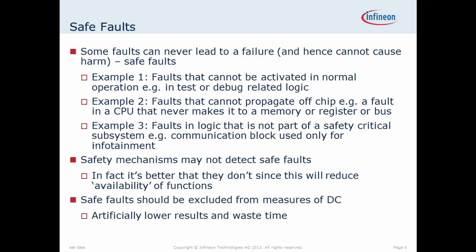So now I come on to safe faults. Some faults can never lead to a failure that can cause harm, and these are called safe faults. For instance, faults that cannot be activated in normal operation. If you have a fault in your test or your debug logic, this is typically turned off during normal operation, and so faults in there typically aren't going to lead to any kind of failure which can cause harm.